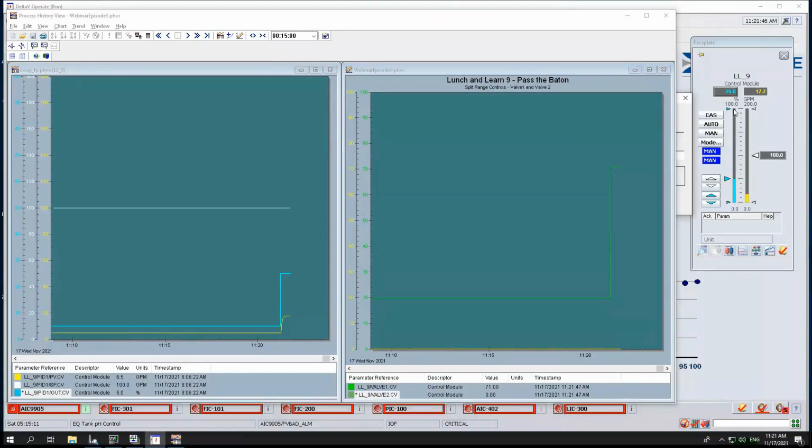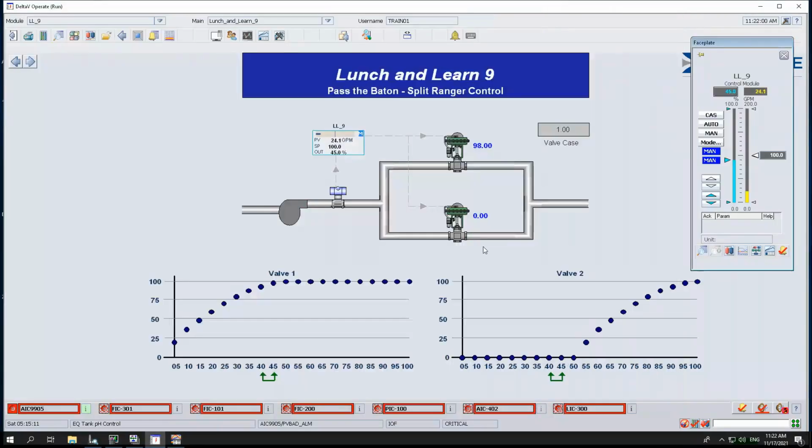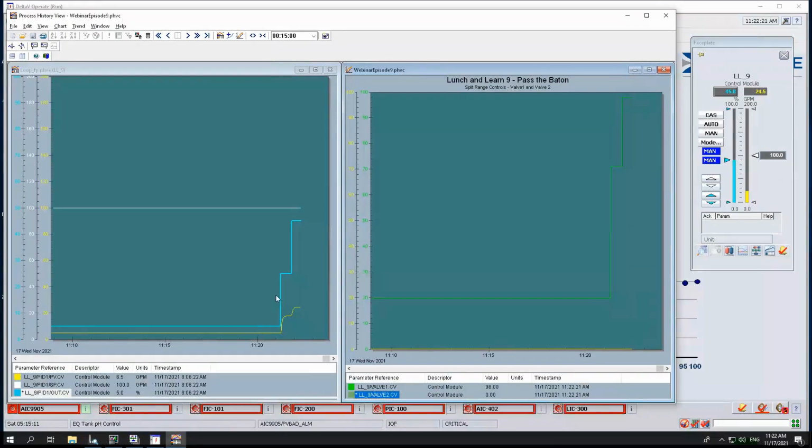So now I'm going to go, let's say, to 45%. Again, the little valve now goes to 98% open. And you can think that a valve is going to give up the ghost at some point. With any valve, once you get to anywhere from 75% open or more, depending on the type of valve, some earlier, some later, the flow characteristic is going to start to taper out. And that's why I use a flow curve here and not the actual valve position. So let me go back to here. I've done my bump. I've moved this little valve and it's almost completely open.